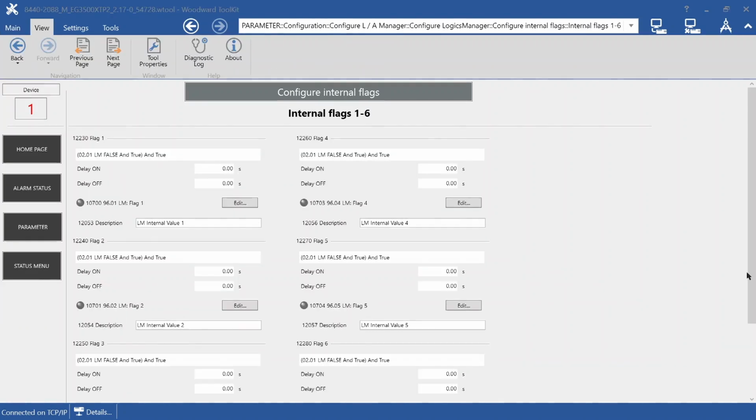Next we decided to use 2 internal flags to latch the low and high state of charge signals. As by time the battery high signal will turn off, because it discharges after some time and falls, for example, below 90%, we want to charge the battery only if the battery low signal triggers. This may be if the state of charge falls, for example, below 30%.